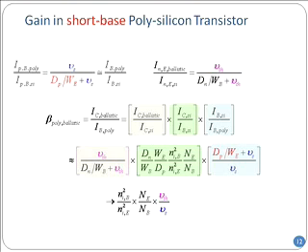However, in this case, as you make the base width smaller and smaller, at some point you get no benefit by making it any smaller or any thinner. And that is what happened in the mid-90s. In fact, that is the point beyond which they have not scaled the base width anymore, about 100 to 200 angstrom in the highest performance transistors today.